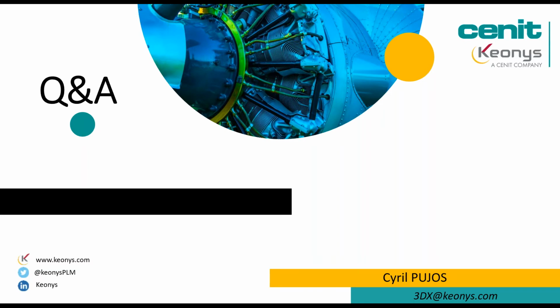Sometimes people have rosette data that they want to use in TrueLoad, so we can force a rosette gauge by stacking 3 strain gauges on top of each other to make them look like a rosette. We don't require rosettes, but people sometimes bring them to us, and we can work with them just fine. By default, we're working with uniaxial gauges.